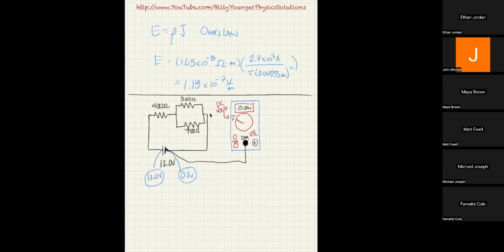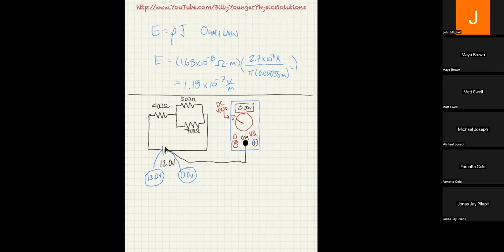Doing this, thinking about this, is a really good thing for helping you figure out a circuit. For instance, we generally assume that wires without resistors on them have very, very low resistance. Heck, you saw last time that we had a mile-long length of cable that was on the order of a couple ohms. So you can see a 400 ohm resistor is a lot different from a wire.